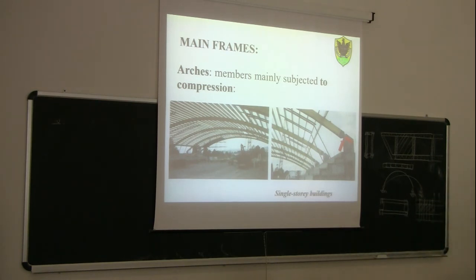And the main internal force will be what? No. No. Two more possibilities. Tension and bending. Okay, tension, last one. Last one is bending. So if we don't prevent this possibility of the arch to enlarge, the main internal force you will find is bending moment. So this arch will behave exactly like a beam. The only difference being that it's curved. So this would be what we call a curved beam.